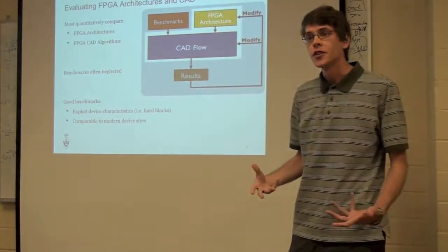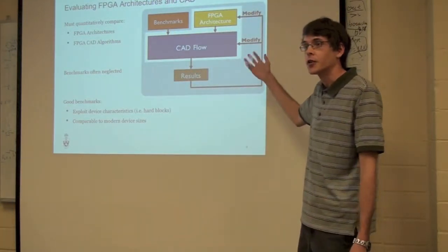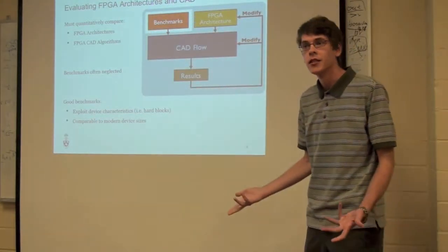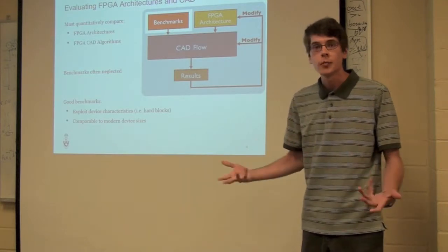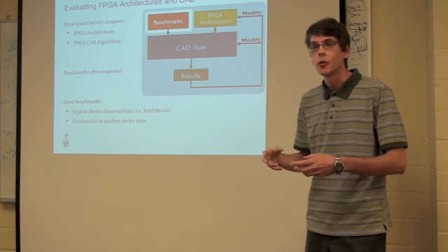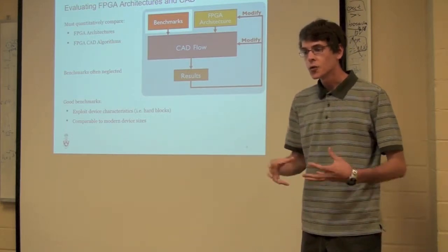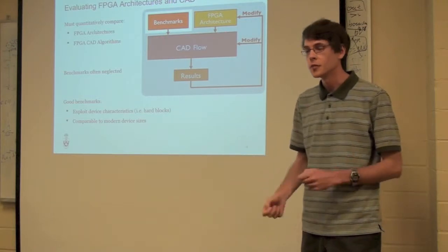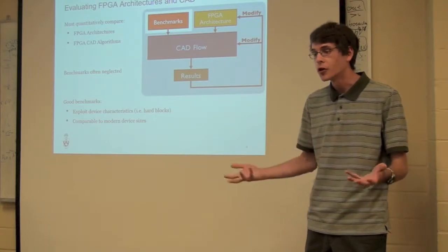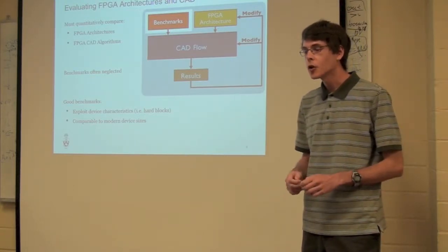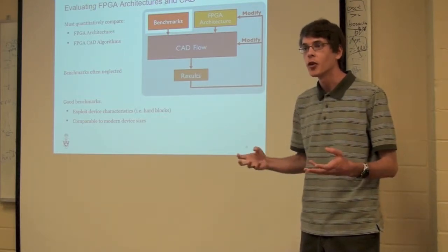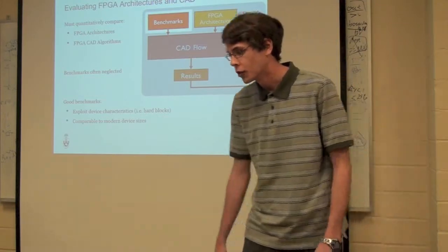So traditionally, a lot of the focus has really been on the FPGA architectures and on the CAD flow. And as a result, the benchmarks have been kind of neglected. But it's important that we have good quality benchmarks when we're doing these kinds of experiments, because we want to make sure that we're optimizing for realistic problems. So some of the things that we might want in a good benchmark set would be benchmarks that exploit device characteristics, so on modern FPGAs, things like hard blocks. And we also want to make sure that they're comparable in size to modern devices, so that we're solving problems on the same scale as exists in the real world.